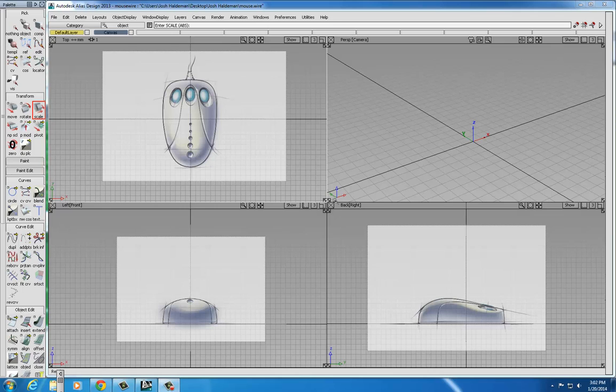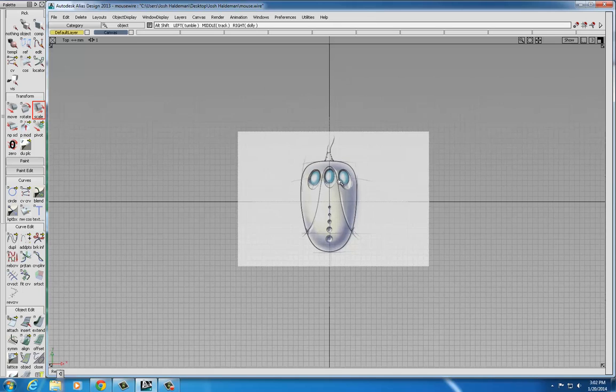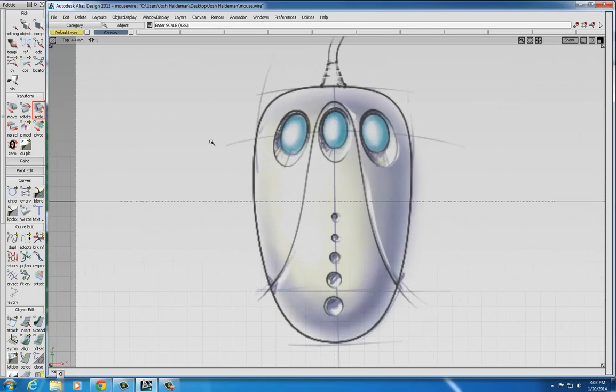To start this tutorial, you want to click in the top view to maximize it and use the Shift and Alternate keys and your right mouse button to zoom in on your model. Next, go over to the palette, go down to the Curves menu, and choose the Circle tool. That's the first one in the upper left. Next, place the circle at these coordinates. You don't need to pick anything here, just type in 0, 0, 0, and hit enter. This will place your circle into your view.